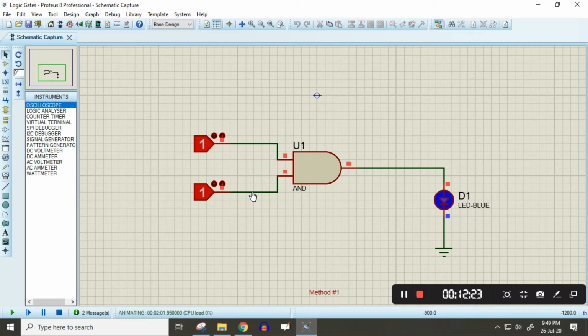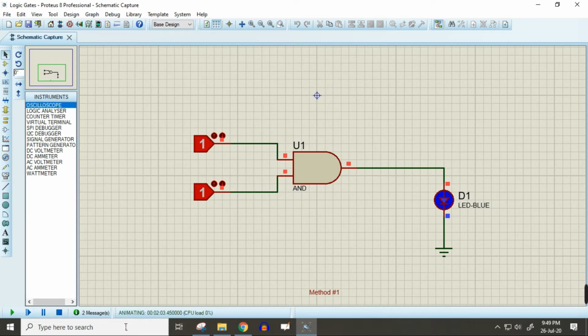As you see, the simulation is still running, and it's showing me time, how long this simulation has been running. If I want to edit something right now, I can just change the logic states. Other than that, I can't change anything. It's giving me a message here: real-time simulation in progress, press ESC to stop.